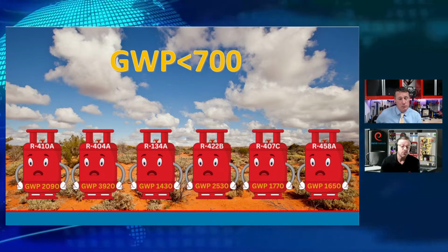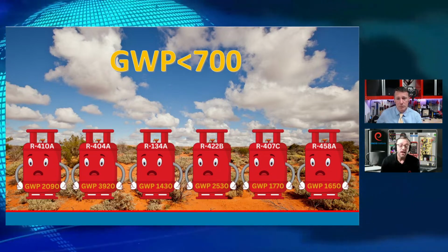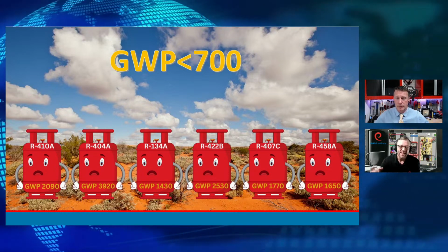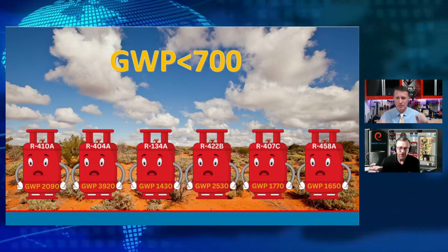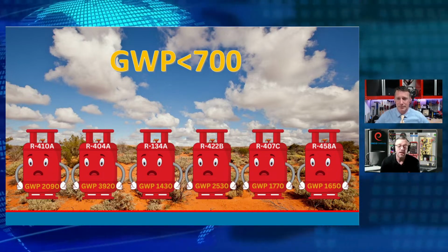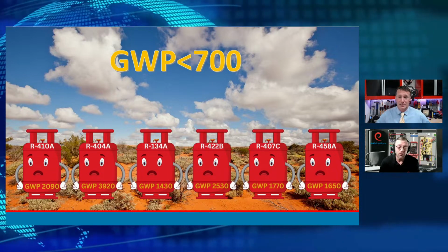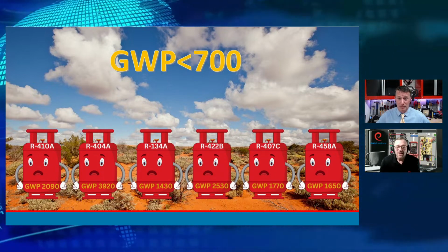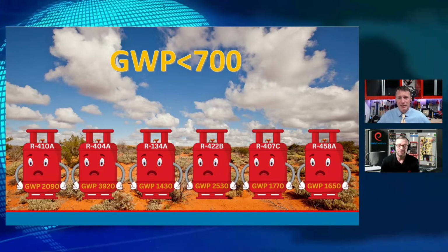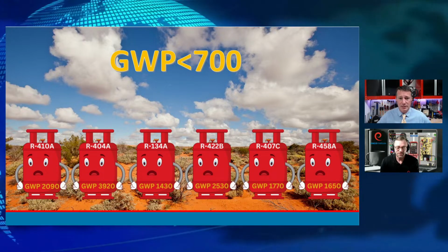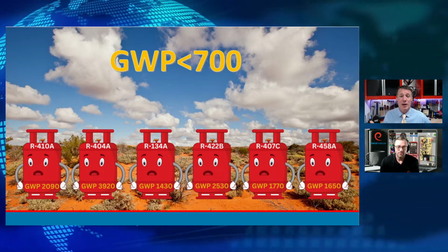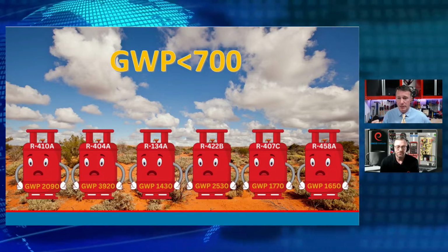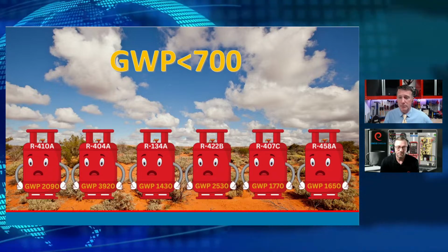So CO2 has a GWP of 1. 410A, when released in the same amount as CO2, can trap 2,090 times as much heat over a 100-year time period than CO2 by itself. Wow. If you look at those numbers, 4048, 3,920, that's huge. And that is our primary low temp refrigerant in refrigeration systems. In commercial refrigeration, we primarily right now are using 134A for medium temp and 404 for low temp. Both of those are going away very rapidly.